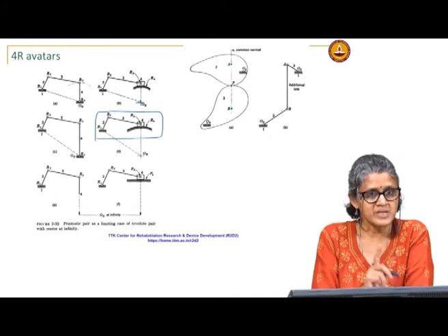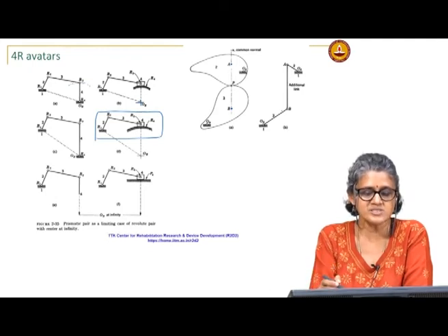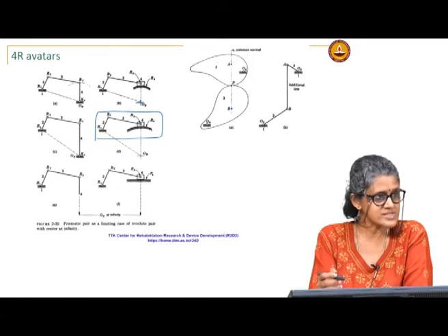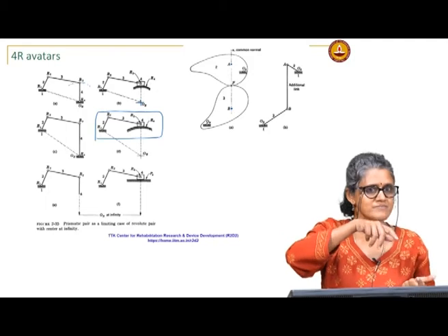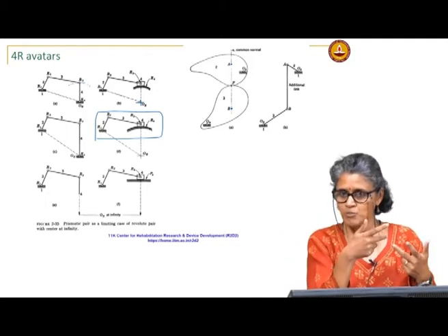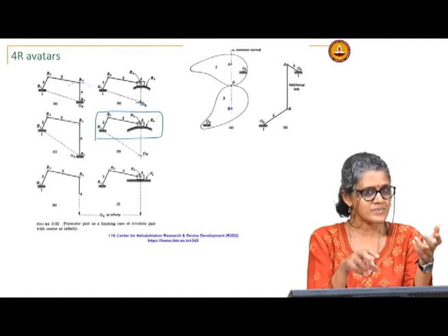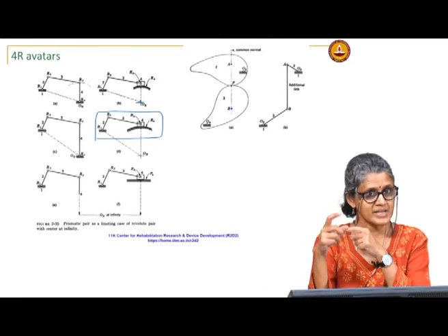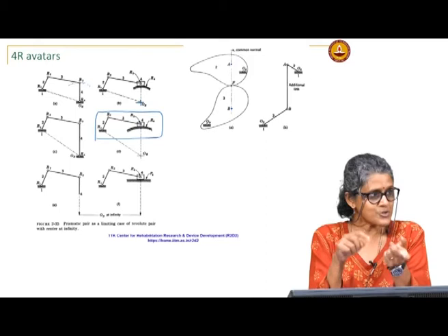An important point to remember is that it is at that particular instant, because one of the things that you can do with a cam follower system is you can constantly change the radius of curvature between the two connected bodies, right. So, at a different instant you will have a different link AB connecting the two. Okay. So, you can use that to analyze.